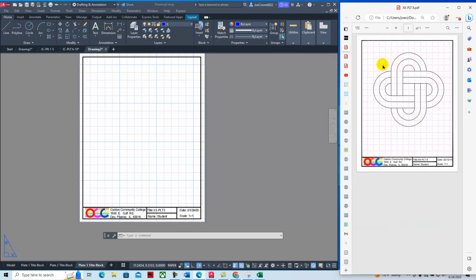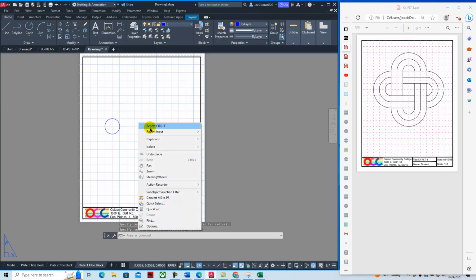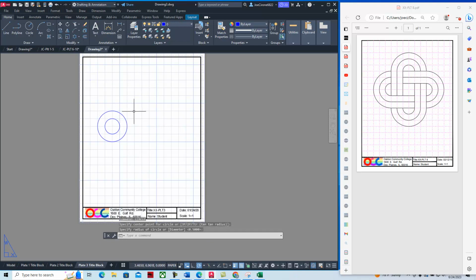So we'll make this kind of a chain type of a shape here. And so as we go and draw this, this is a good example of one that you can draw geometry that you're going to erase or trim rather than try to draw all these as arcs. It's easier to draw them as circles and then to cut them in half. And so we can go and we can start off by drawing a circle. And then we can draw the other corresponding circles.